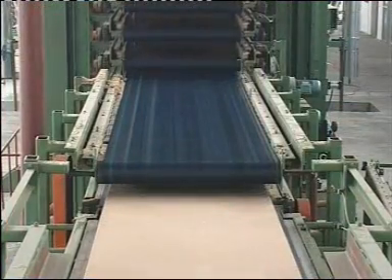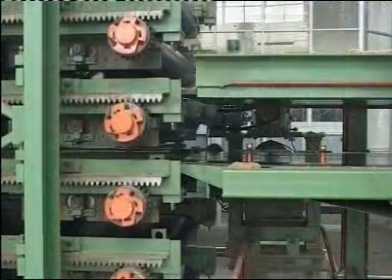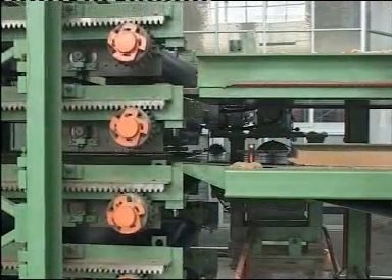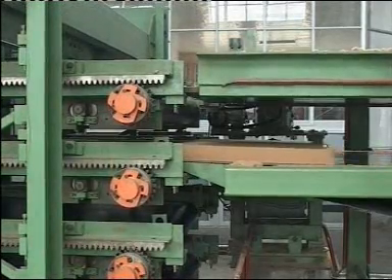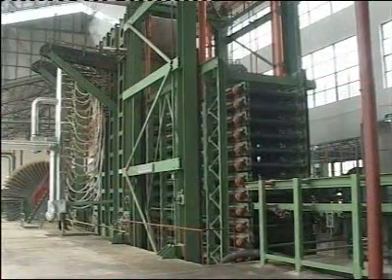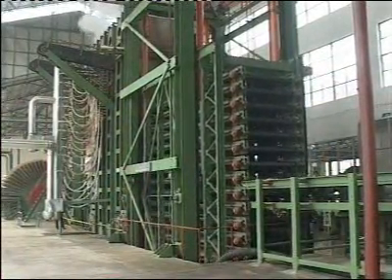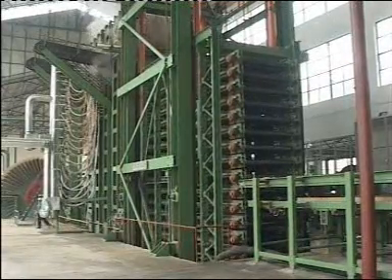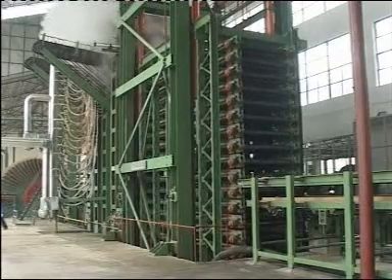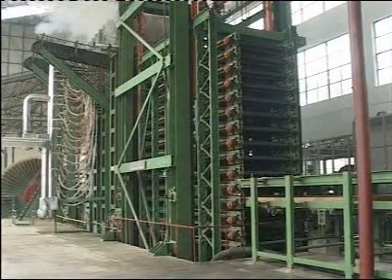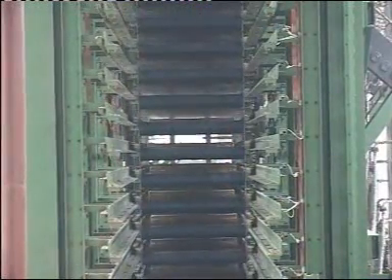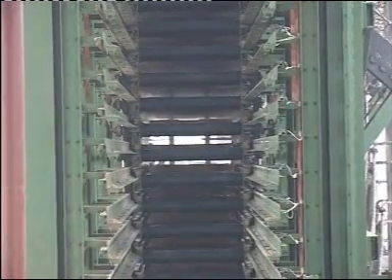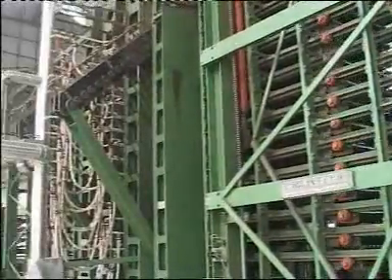When loader is lifting, the mats are stored on preloader and transported in loader simultaneously when loader is at work position via synchronous conveyor. The loader is equipped with collarless belt tray. The mat on the loading conveyor is loaded into the loader one by one. When each deck of the loader is loaded with mat, all belt trays with mats will be simultaneously discharged out of the loader and then fed into the hot press.